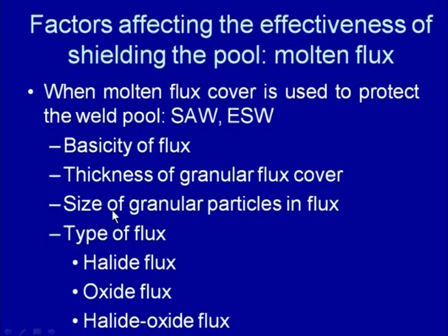So, depending upon their ability to withstand thermal stress and their ability to decompose at high temperature, and these factors are influenced by the size of the granular particles, accordingly they affect the protection to the weld pool.